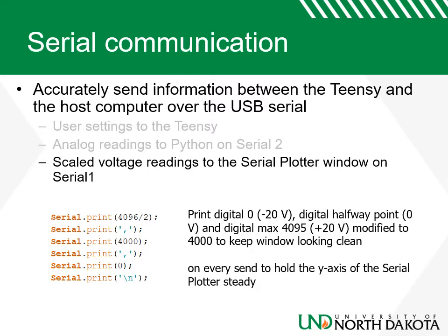The serial plotter y-axis is not settable, so to hold the screen steady, I print a digital 0, the digital halfway point, and the digital max, which was modified from 4095 to 4000. This kept the window looking a little more clean.